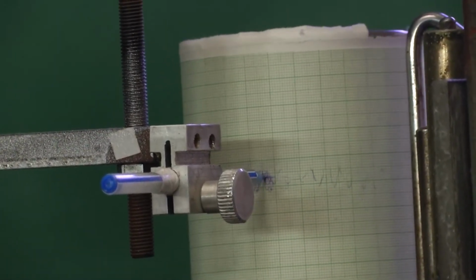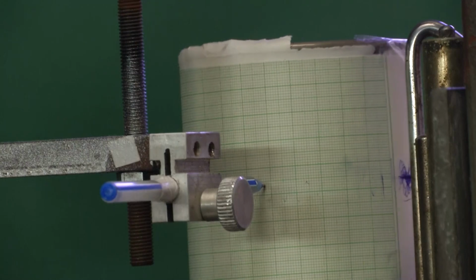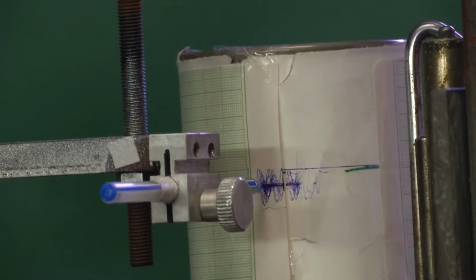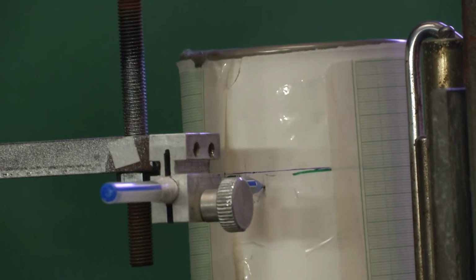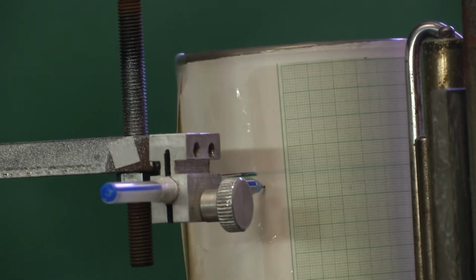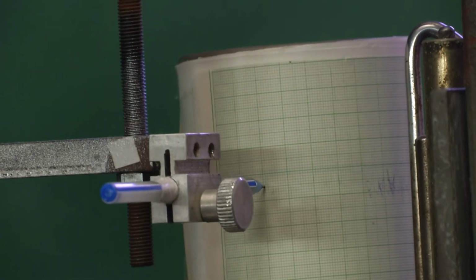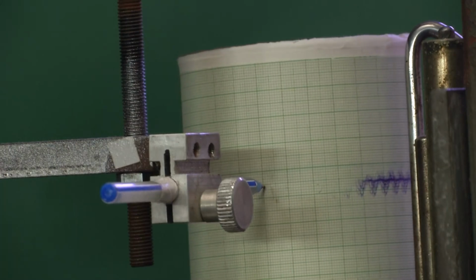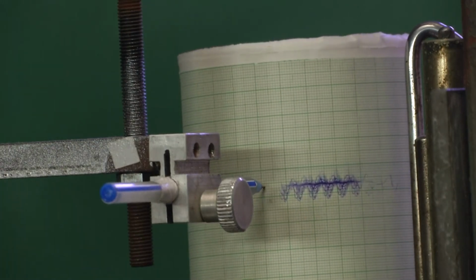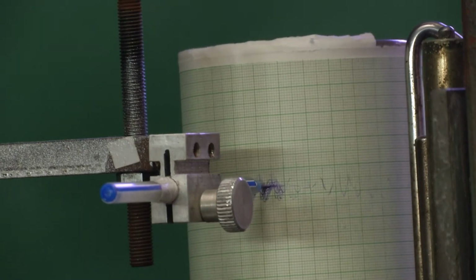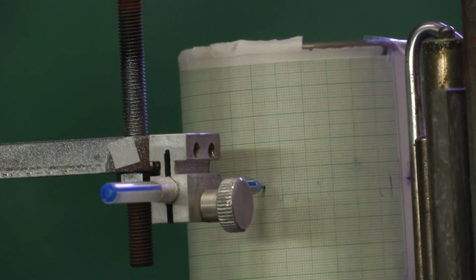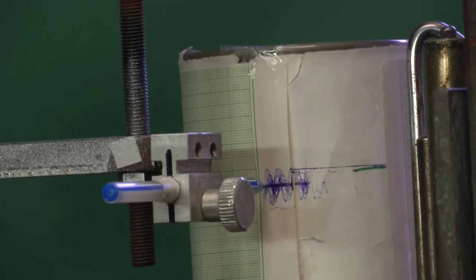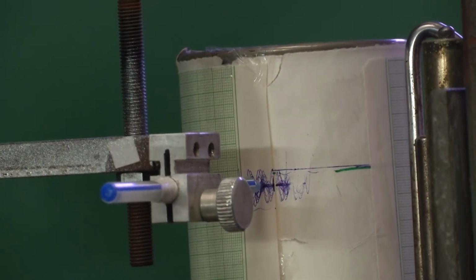So, the amplitude versus time plot, and if we get that time displacement plot, of course, we can not only find the number of oscillations in a given period of time, but also based on the decay of the vibration, we can estimate the logarithmic decrement as we discussed. So, using logarithmic decrement, we can have an equivalent viscous damping coefficient, damping factor to be obtained.